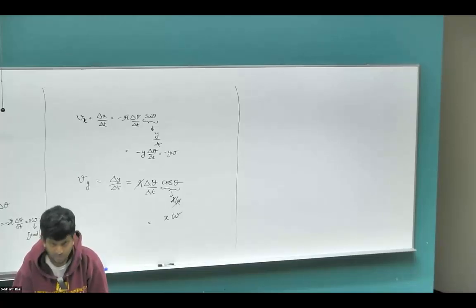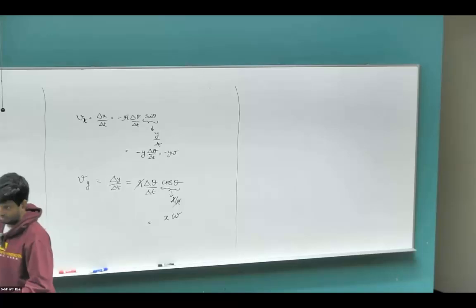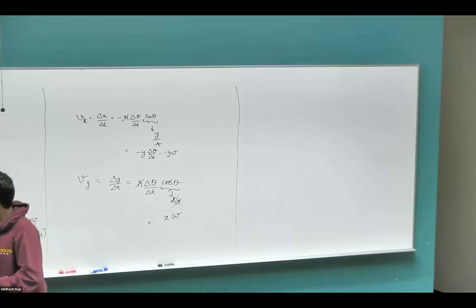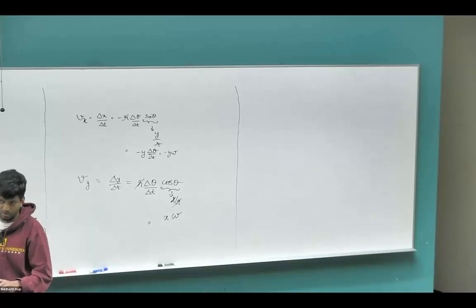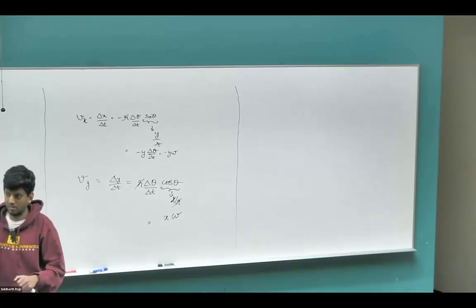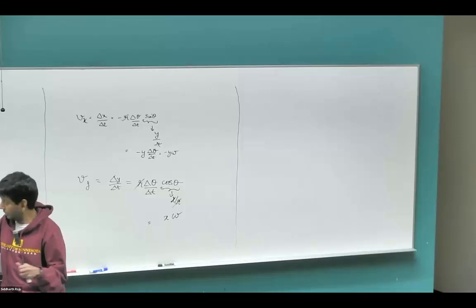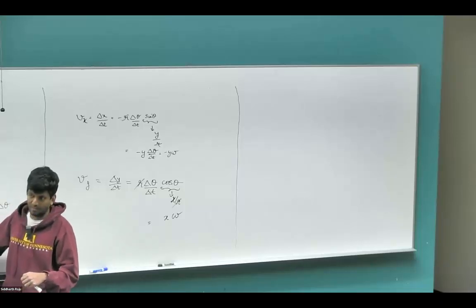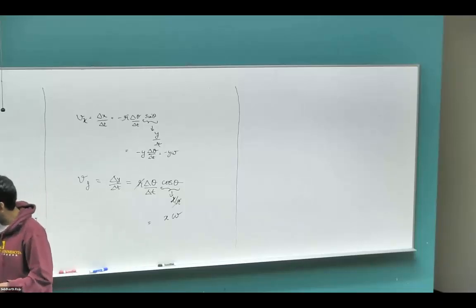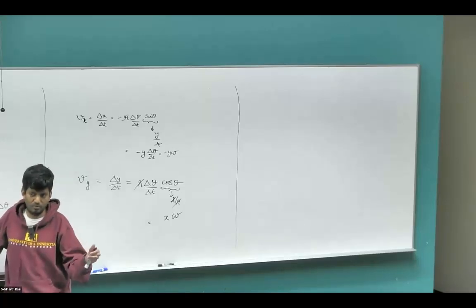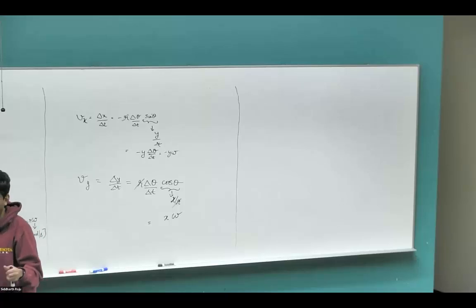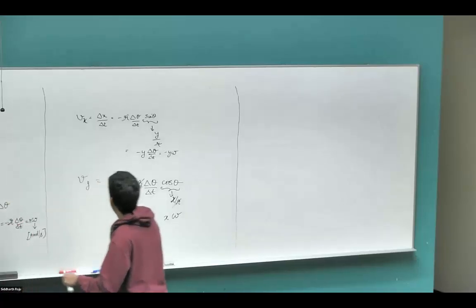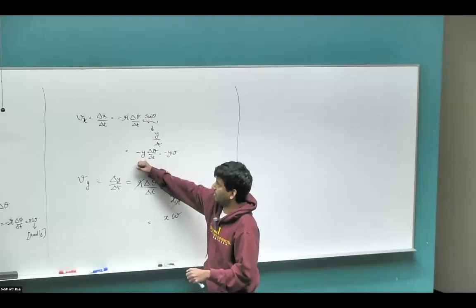There's nothing magical about it. It's purely just the trigonometric nature of our arrangement, right? So the projection of this is going to be sine of theta, but as this rod rotates, what is the rate at which that's going to vary? Sorry, the projection of this is going to be cos of theta, and the rate at which the projection changes is going to be the differential of it, which is going to end up being negative sine of theta. And negative sine of theta itself is the y component. All right, so that's all the cross coupling term is explaining.